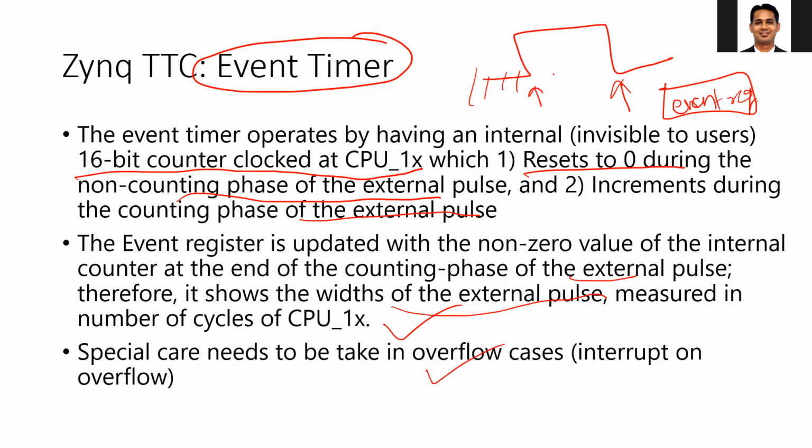For example, suppose that the total number of clock pulses required is 24, but you use only the 4-bit counter. So what we'll get is that after you go to the 24-bit counter, it will become 0 somewhere, and at the end you will get only the value, say 8. And then you will find out the clock pulse as per this value 8, which is wrong, right?